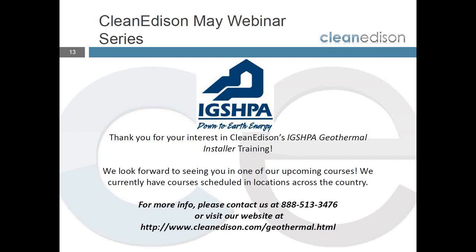ground source heating, the open loop. IGSPA trains in closed loop technology, where the water circulates, and the same water that was put into my system 4 or 5 years ago now is the same water that's in there now. It has a little propylene glycol biodegradable antifreeze in it, and it just keeps circulating that same water, getting warm and cool, warm and cool, warm and cool.